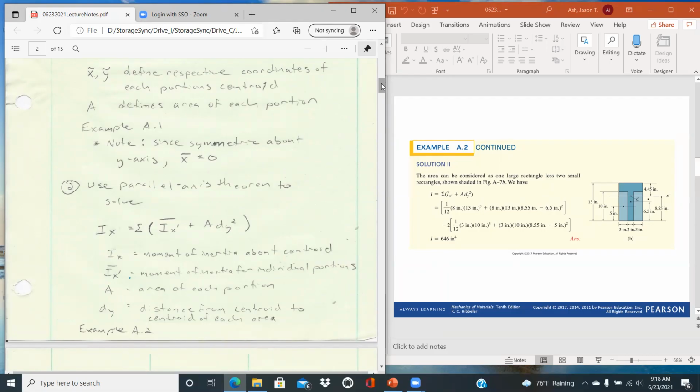Yep. And so also just remember, that's my go-to source. If I ever have to do this, I tend to just go to the back of Hibbeler's textbook just to refresh my memory, because this is something that I don't often do. The things that I have committed to memory are just what the area moment of inertia is for a rectangle, bh cubed over 12.